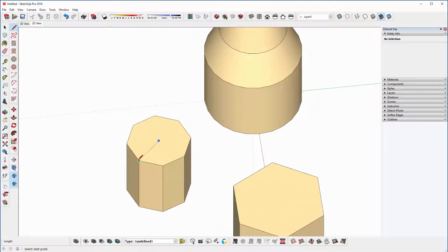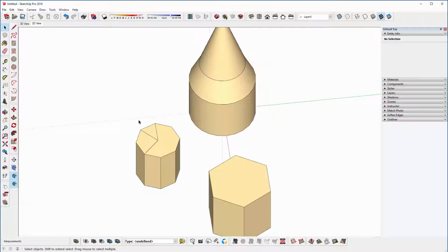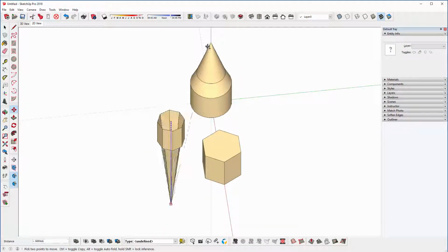So just like the cone, I could start from the center point, create 3 edges. It should be enough. Let's give it a go. I'm just testing this for the first time. Click on the midpoint, up arrow. No, we need to break it up into more segments. So if we break it up into all segments, just with the line tool, get the move tool, up arrow, we can actually reference other points.